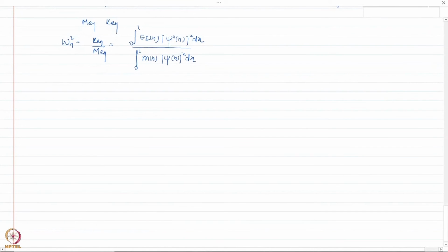For example, typically if we have, let us say, a cantilever beam, something like this, and a load is being applied, let us say at one end, we used to simplify this system to a spring mass system, saying that I'm going to assume my K equivalent to be 3 EI by L cube and then mass to be represented by tributary.